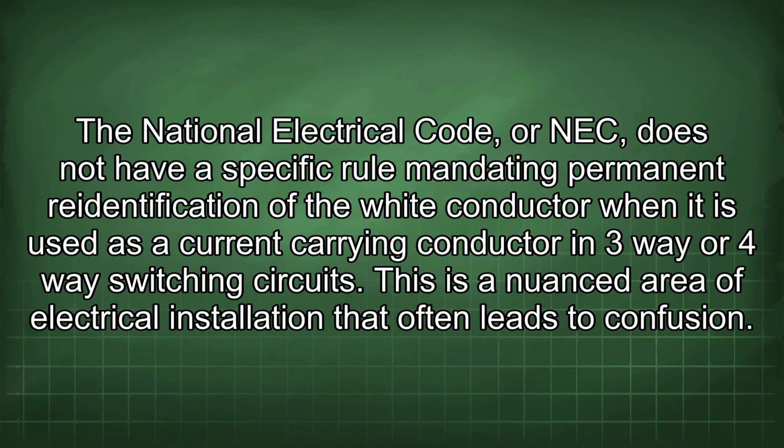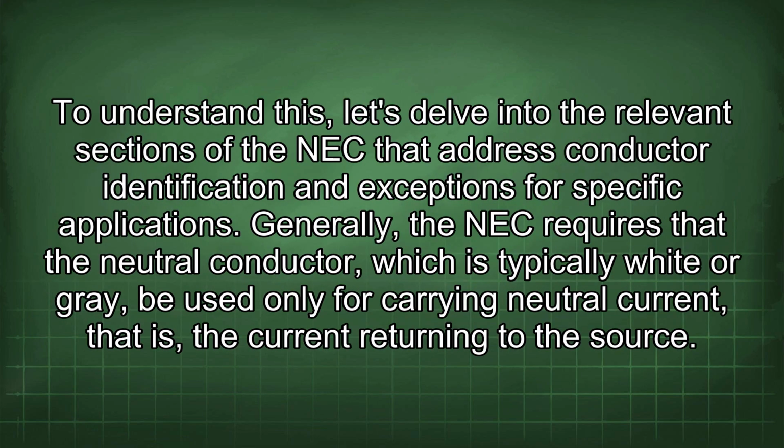The National Electrical Code, or NEC, does not have a specific rule mandating permanent re-identification of the white conductor when it is used as a current carrying conductor in three-way or four-way switching circuits. This is a nuanced area of electrical installation that often leads to confusion. To understand this, let's delve into the relevant sections of the NEC that address conductor identification and exceptions for specific